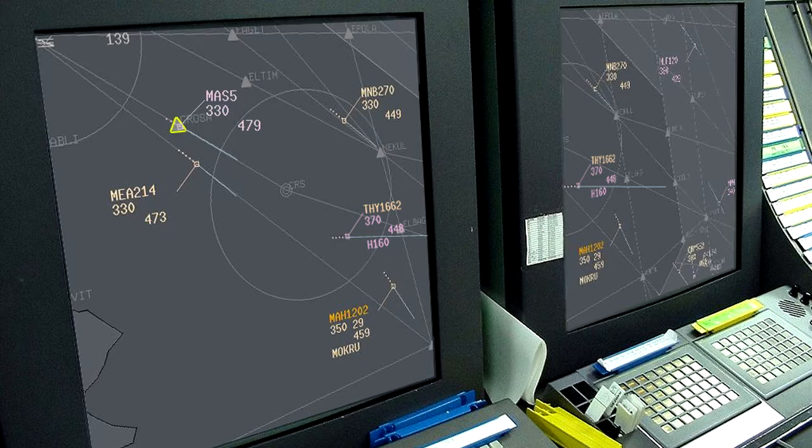designation of the radar position indication by reference to, or in terms of, bearing and distance from a geographical position or navigational facility accurately indicated on both radar displays, together with a track of the observed radar position indication; instruction to the aircraft by the transferring controller to change code, and the observation of the change by the accepting controller; instruction to the aircraft by the transferring controller to squawk ident, and observation of this response by the accepting controller. This completes the methods by which air traffic controllers transfer radar-identified aircraft.